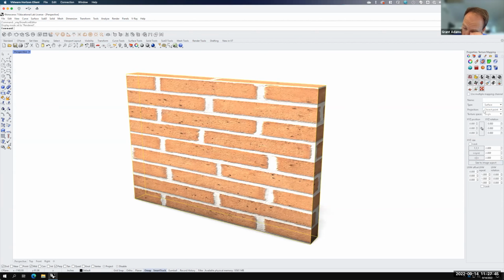So one of the best places to start when it comes to texture mapping is to identify what type of object you have. Frequently, you have an object that exists as a primitive object, a primitive shape. This object is very close to a block. So let's use our box tool and apply a box mapping. Over here in the texture mapping little window, we're going to go over to the apply box mapping tool. I'll go ahead and click on it.